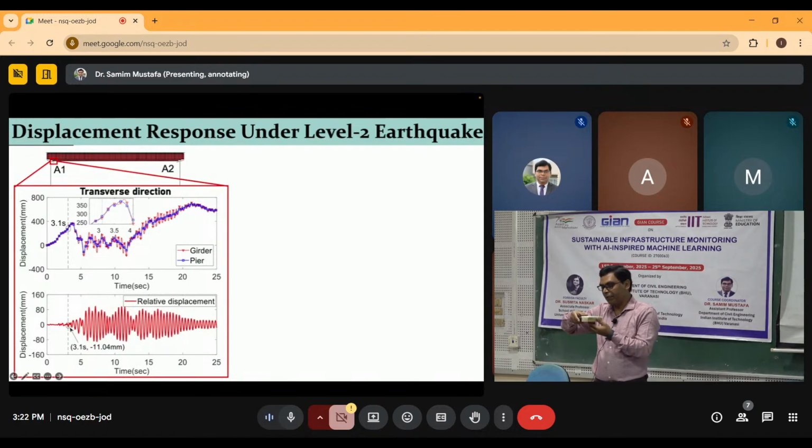The objective of the side block is to resist the transverse movement of the bearing during the earthquake. Because of the ground motion, there will be vibration and it dissipates by deforming. So as much as possible, it resists the transverse direction ground deformation.